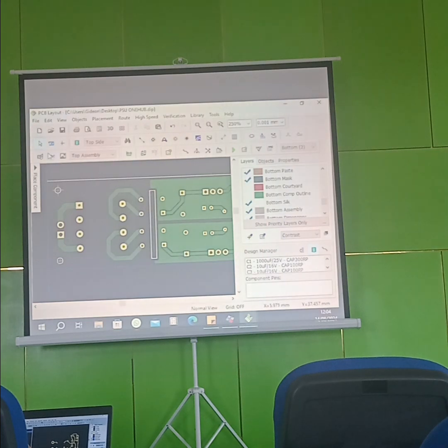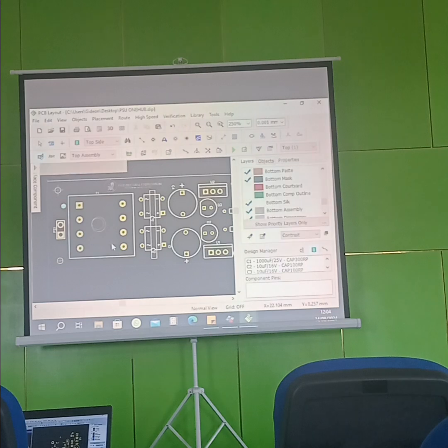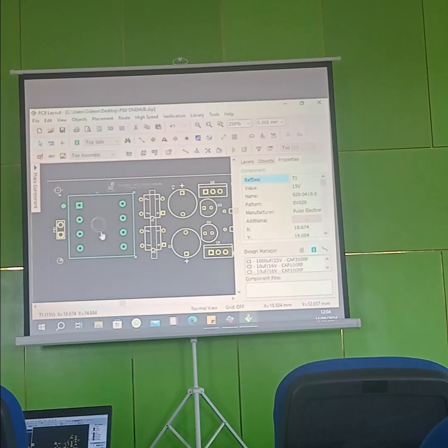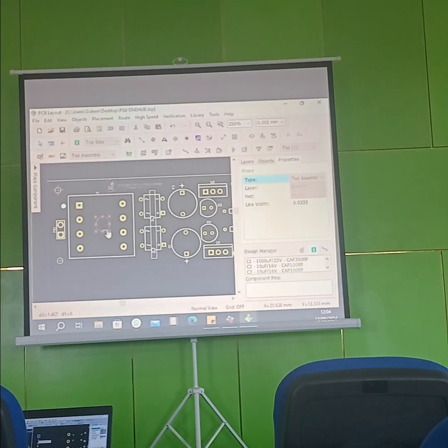I just draw a shape. That's all I did. Look at it. Any shape here you can draw. Okay, let me use this now. At the top no matter here. You understand? You draw it at the top. Oh, Ctrl Z. Look at this now. I want a hole here. It is just a normal shape as it is. And it's a top assembly. So you can come and you see, I've changed it to board cutout.